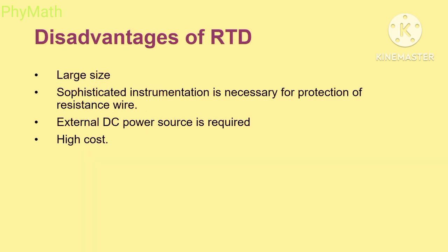Which are the different disadvantages of RTD? First, the large size. Second, sophisticated instrumentation is necessary for protection of resistance wire. Third, an external DC power source is required. And fourth, high cost.